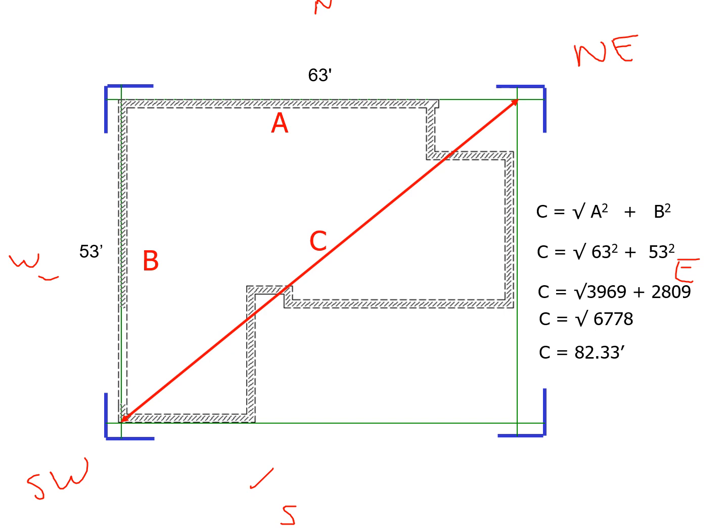Now, that's 82 foot 4 inches. So if I took the same tape that I have measured here, and I don't move anything, I hold my hand on 82 foot 4 inches. I'm going to turn it around and measure from here to here. Well, from there to there. You get what I mean? And it has to measure 82 foot 4 inches. If it measures anything other than 82 foot 4 inches, you're not laid out square. You're off somewhere. You're not at a 90-degree angle here. So you have to go back and adjust till you are. Okay, which you know that.